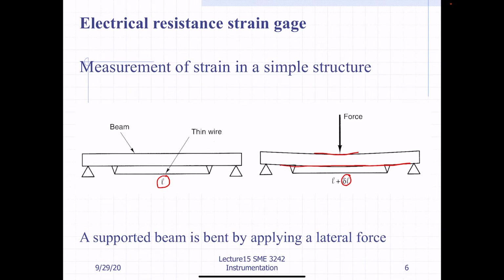From the deformation, we will be able to calculate the strain, equal to delta L per L. A common unit for strain is microstrain, and strain value is unitless, meaning there will be no unit for the strain. For example, a low-strength steel yields a strain of 1,400 microstrain, which is equivalent to